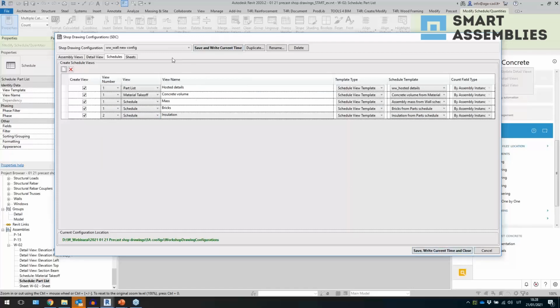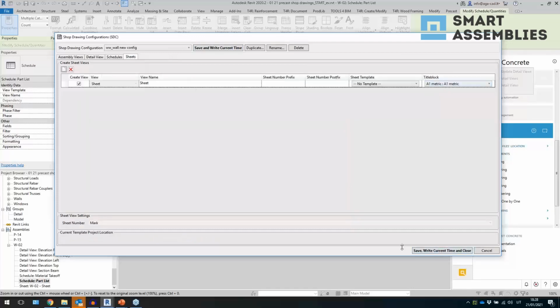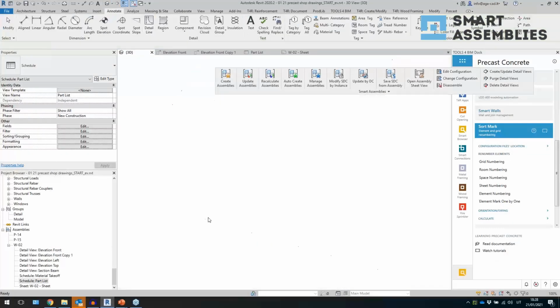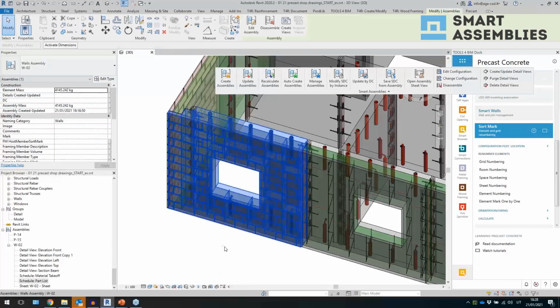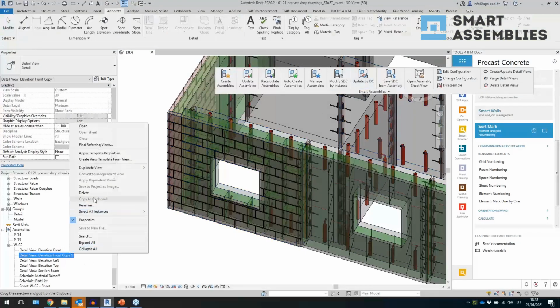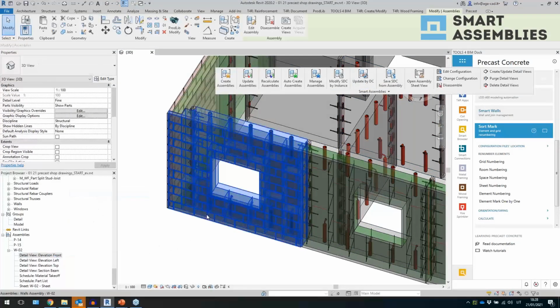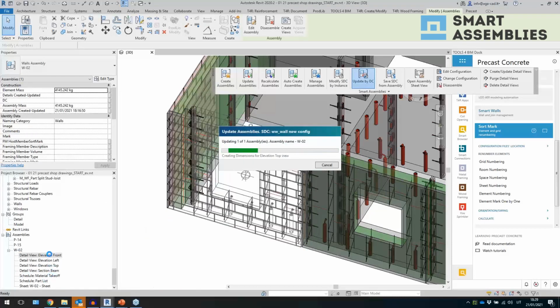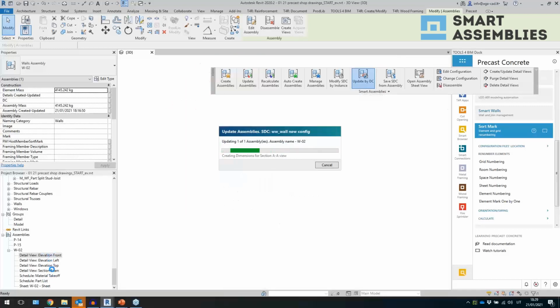So all right, save the sheet. I have title block, just selected one of them. Again, this is Revit family, so it could be any kind of template family, right? So I'll delete that one. Maybe I don't need that. And let's update by DC, so update by latest drawing configuration settings. It's going to apply everything what I had, all these scales and so on.